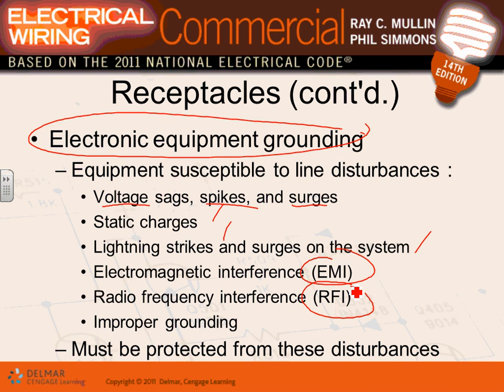For anything that has solid state electronic equipment in it, to increase the survivability of this equipment, we need to do two things, ladies and gentlemen. Number one, we need to have an isolated ground receptacle so we do not drag all the noises, the signals into the chassis of the equipment and make it interfere with the proper operation of this equipment. Number two, we need to get rid of the spikes and static electricity, and we do this through grounding as well as through surge protective devices.